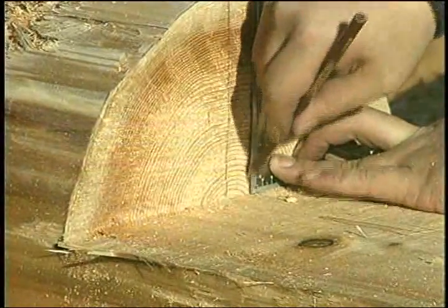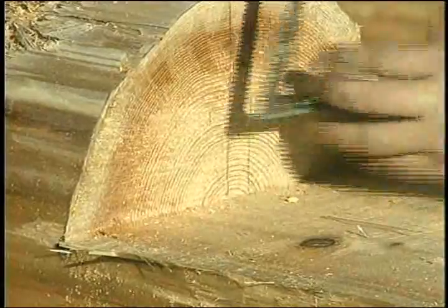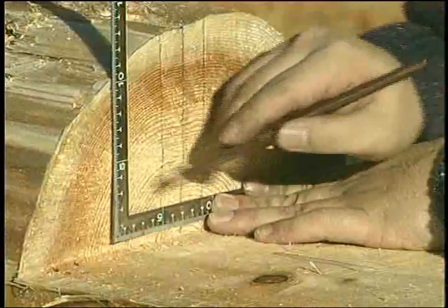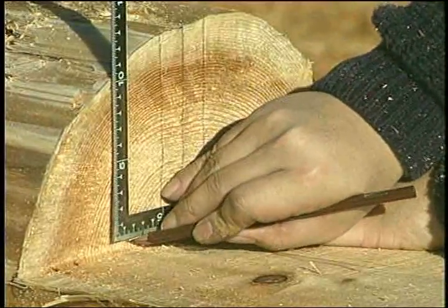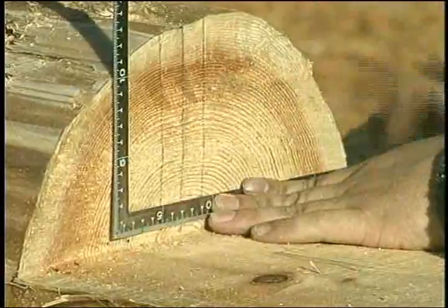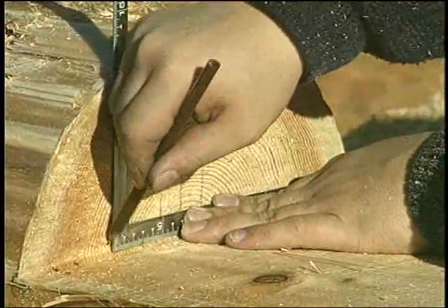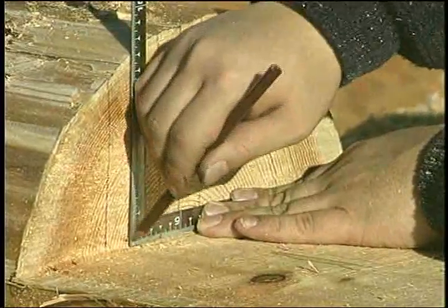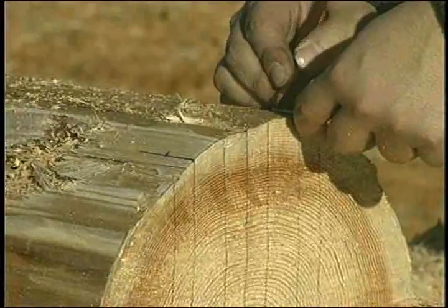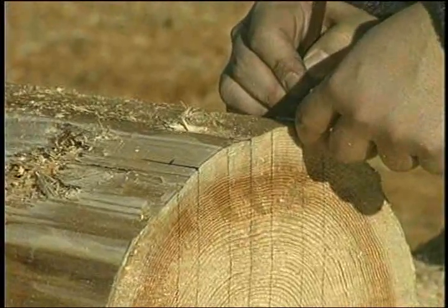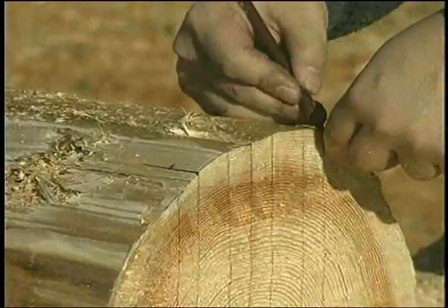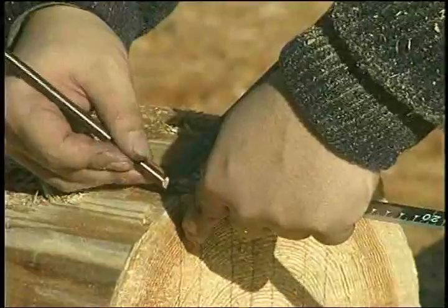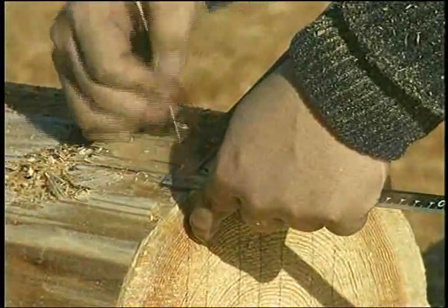Draw the center line down the log end and work from that. Measure in the width of the keyway, the width of the window frame, and the width of the trim on each side. Measure in the depth of these cuts. The accuracy of the original cut will affect the ease of this layout, and a smooth, straight cut will help maintain your standard of accuracy. If your window frame is very narrow, you may have to adjust the center line for the window so that the end of the groove in your log is covered.